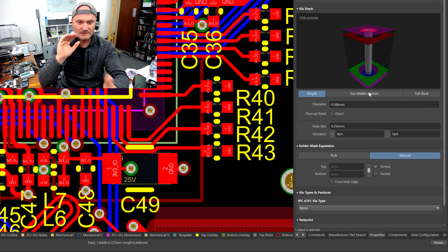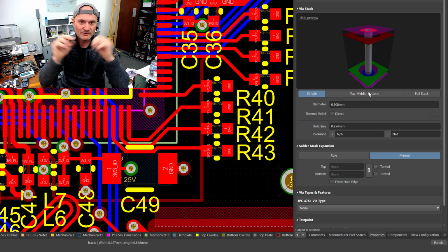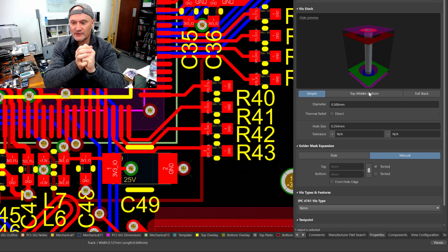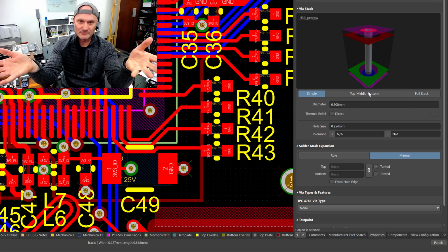So you would not only define the top and bottom pad size for a via or a through-hole component pad, same thing, right? You would also define the anti-pad, they call it, in some of those other tools. So in Altium Designer, it's just a clearance, and clearances are also rules-driven.